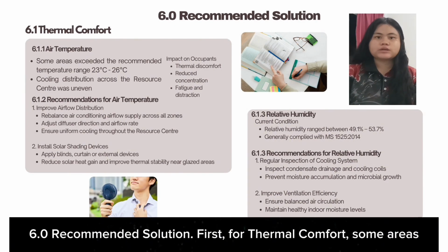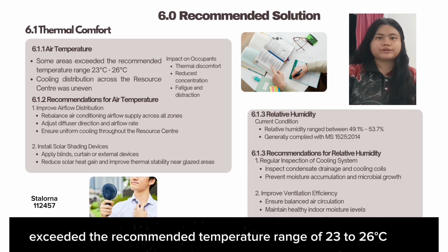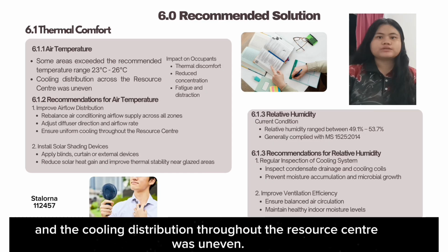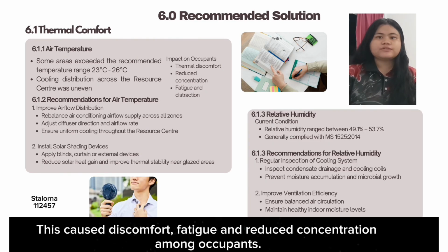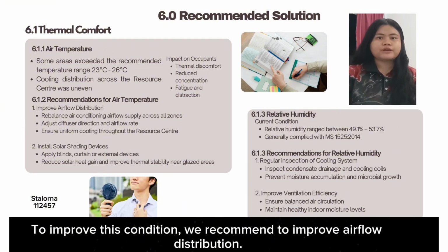6.0 Recommended solution. First, for thermal comfort, some areas exceeded the recommended temperature range of 23 to 26 degrees Celsius, and the cooling distribution throughout the resource center was uneven. This caused discomfort, fatigue, and reduced concentration among occupants. To improve this condition, we recommend improving airflow distribution.